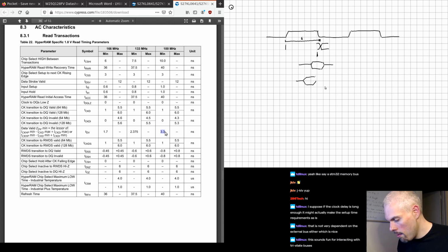Could be there. Could be there. You don't know. And so for that kind of device, you essentially have the same thing for DDR and DDR3 and stuff like that, all fast memory buses. You're guaranteed a certain data valid window. You just have absolutely no idea where it is. And that's where you need to use memory training.